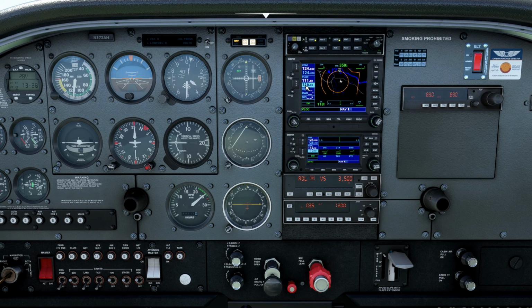If you lose the signal like I just did off the VOR or a localizer, if you fly out of range of that signal, or also if you're passing over the VOR, if you're getting into the cone of confusion, when you pass, if you're flying a radial into a VOR and then navigating on the same radial or the opposite radial on the way out of the VOR, you can't just leave it in nav and pass over the station. It's going to revert into wing level mode, or you're going to have to put it into heading mode. And then on the other side of the VOR, you'll have to re-engage the navigation mode.